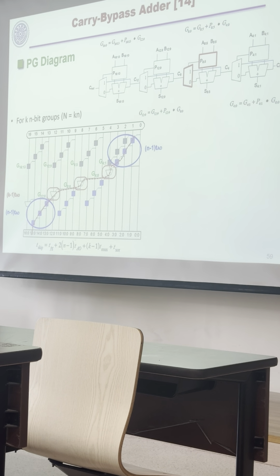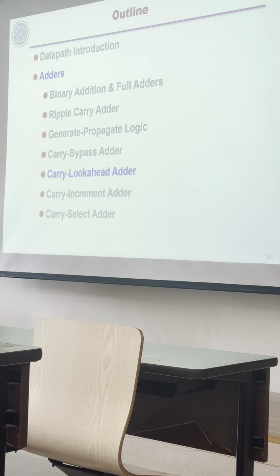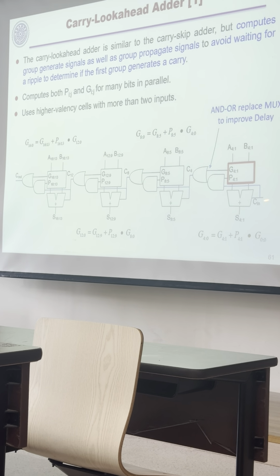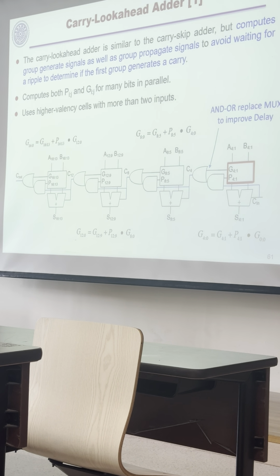Key is here. But you need to explain this one. It cannot be just remember this one. You need to understand what's the operation concept. Why can it be faster than the ripple? And then look ahead, where we calculate more items here. The key of this look ahead is to calculate G and P, both. And then we pass this multiplexer by this N row, and this input still goes to the N here.